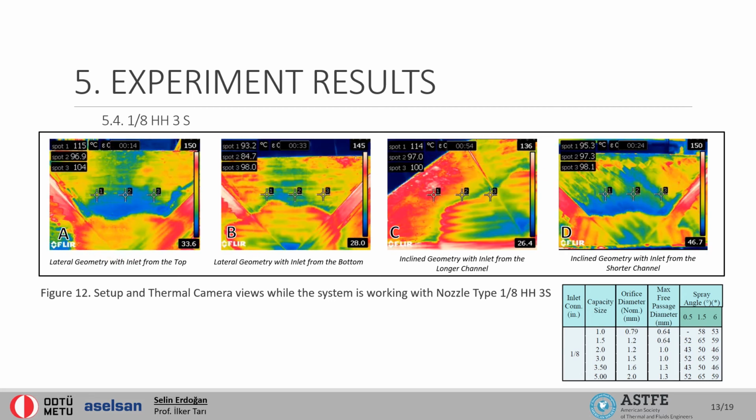With the fourth nozzle, a flow rate of 3.1 liters per minute and a spraying angle of 59 degrees is obtained. There is an inconsistency between the sprayed fluid boundary on the surface and the nozzle angle. From the image, it seems like the angle is too low compared to the previous nozzles. However, the previous nozzles had lower angles.